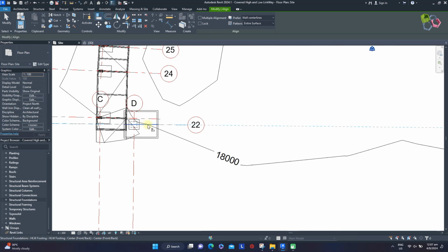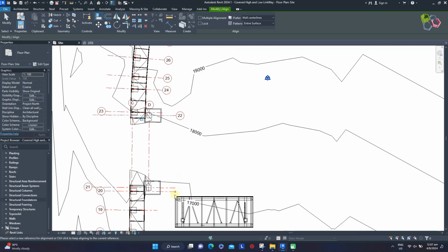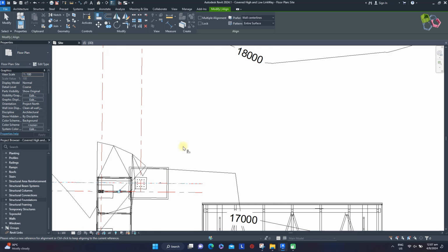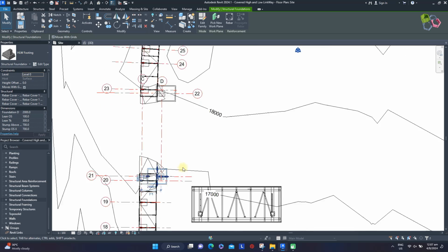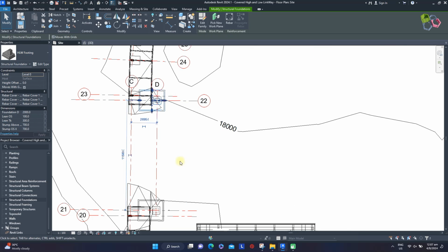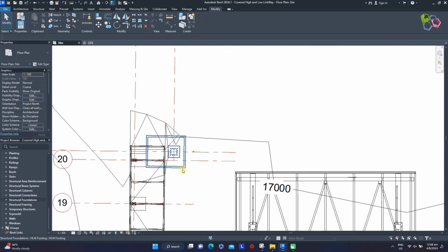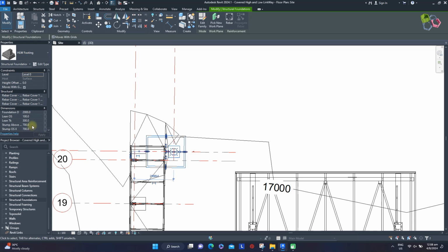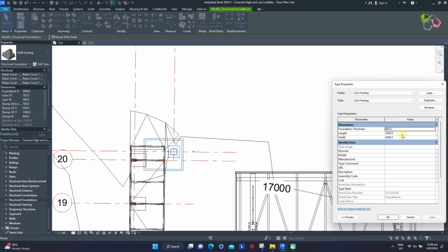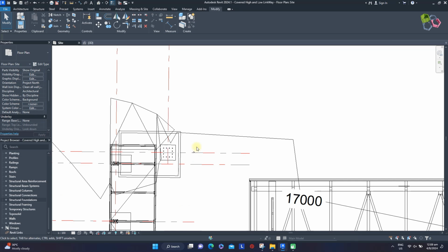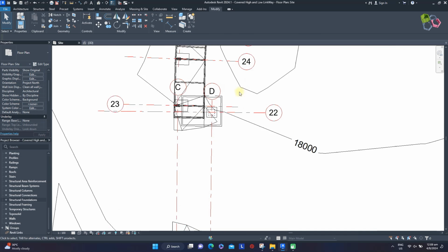And the last two footings, align and rotate as well. The last footing stays inserted, applying some parameter values in the properties panel. Stamp offset Y 1200, stamp offset X 550, and go to edit type, length given 3000 mm, width 2200, apply. OK. Next for the 14 on the grid 22.